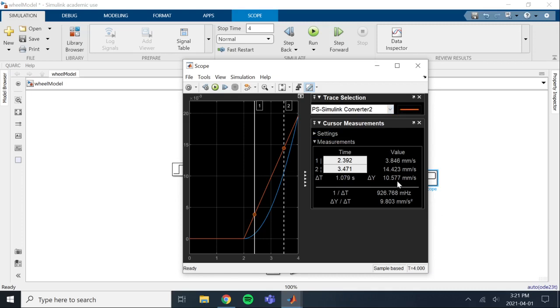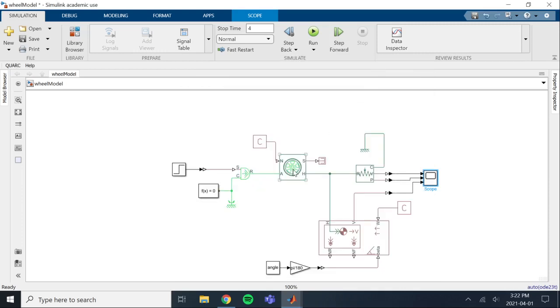We're getting up to speeds around, let's see, maxing out at around 15 millimeters per second. That's nothing special. It's pretty slow still. So that's mainly attributed to the fact that this tire is slipping a lot. And it's not able to push the rover. It doesn't have a whole lot of torque, so it can't actually move the rover's body.